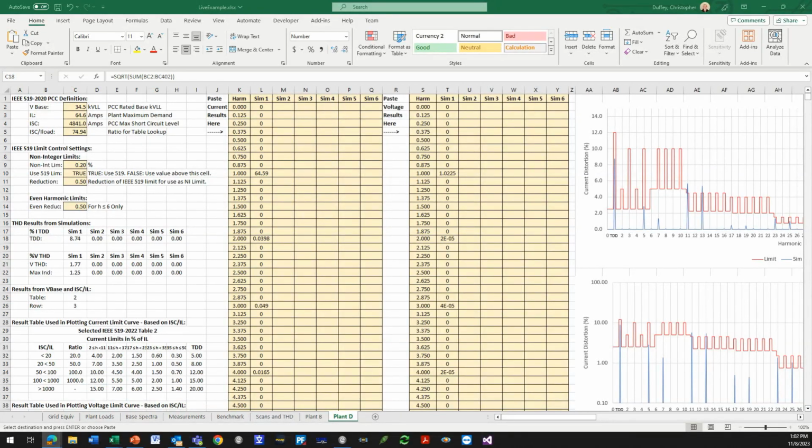Okay, regarding harmonic compensation, will the filter be installed near the nonlinear load or at the PCC point? Both or either. It's going to depend on your application and your budget and what you want to accomplish. I like filtering as close to the load as possible as long as it's reasonable. However, if you had 10 sources and all 10 were connected to the same 13.8 kV bus, it would be more cost effective to filter all at the same time at the bus with one filter bank.